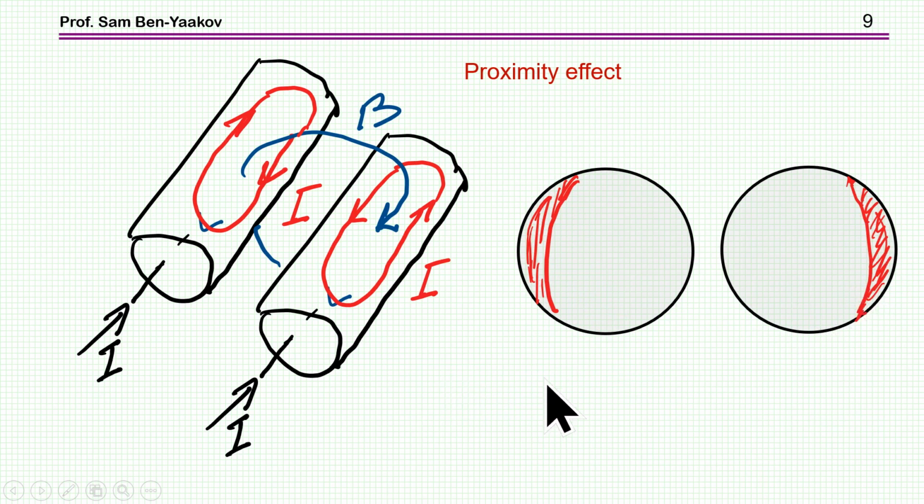Again, here RAC will be larger than RDC, of course, and depending on the frequency, we're going to lose quite a bit of area here, which makes the resistance high, and therefore the losses will be high at high frequency.